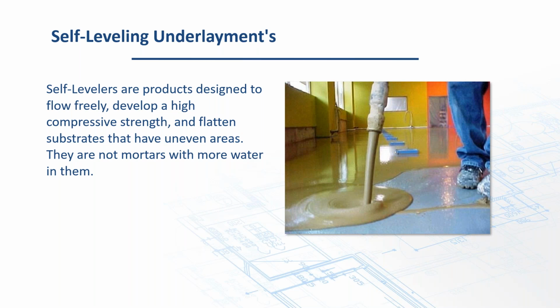So it's critically important that you use the proper water to powder ratio. The other thing I wanted to mention about self-levelers, we call them self-levelers. Quite often, that's not how they're used. They're used to just get us within our floor tolerance, not to actually level a floor. In other words, make it flatter to accommodate an installation. We'll talk more about that.